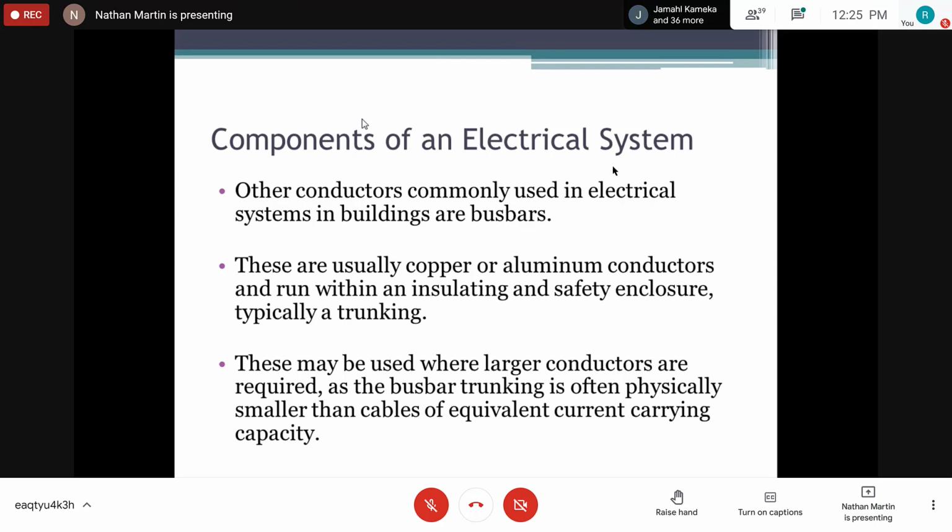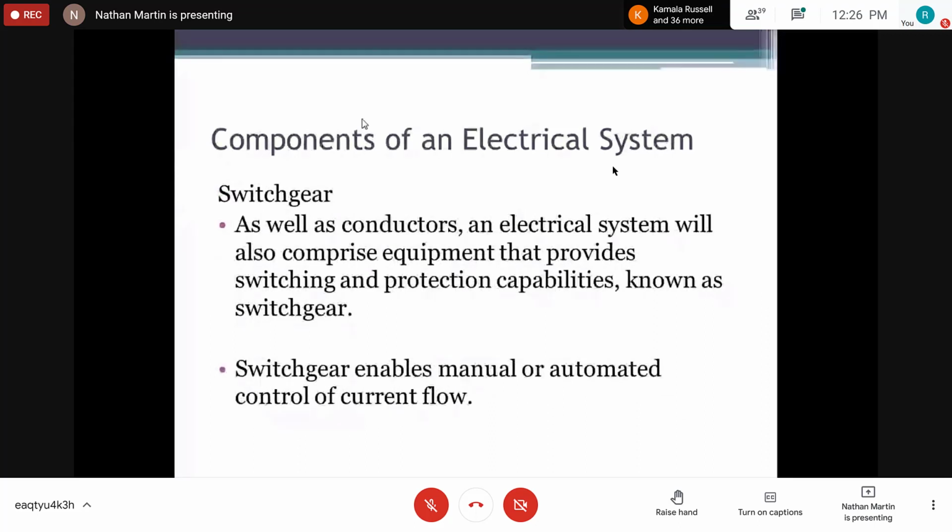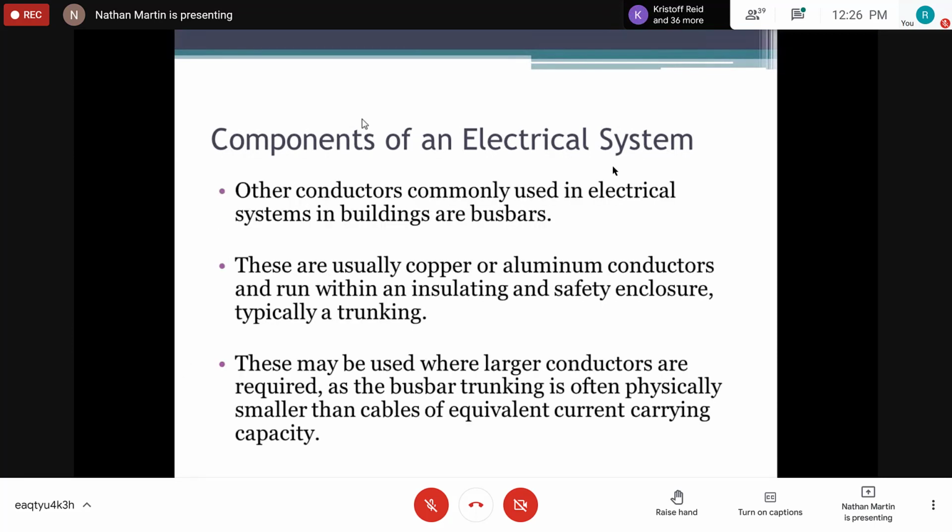They just have the bus bar trunking, and it looks much better. All right. So when we come to the switch gear, right? Sorry. The bus bar trunking you talked about, is that the aluminum metal one? Yes, but the bus bars are insulated from the metal by either ceramic material or thermosetting material, right? So you either use ceramic or thermosetting.